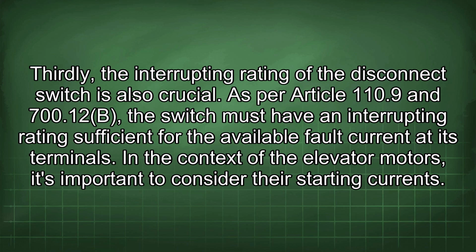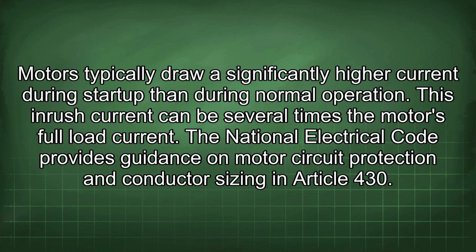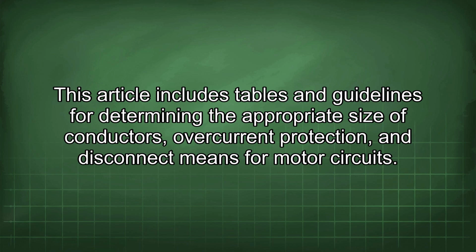its terminals. In the context of the elevator motors, it's important to consider their starting currents. Motors typically draw a significantly higher current during startup than during normal operation. This inrush current can be several times the motor's full load current. The National Electrical Code provides guidance on motor circuit protection and conductor sizing in Article 430. This article includes tables and guidelines for determining the appropriate size of conductors, overcurrent protection, and disconnect means for motor